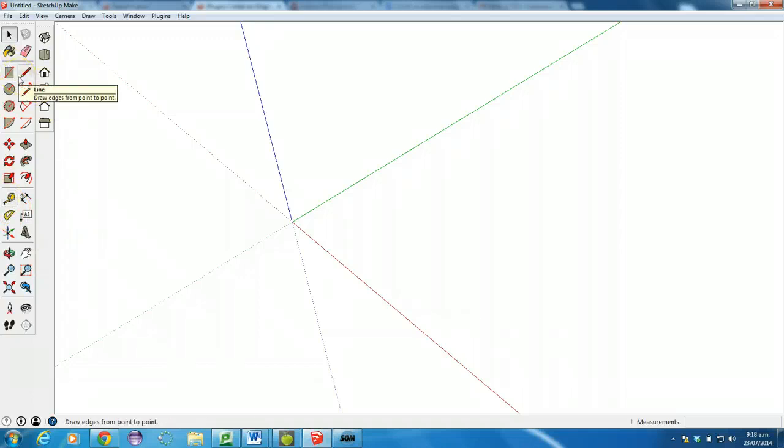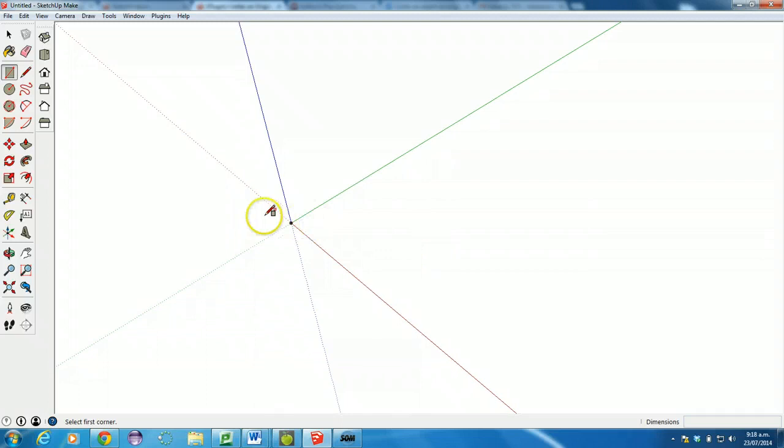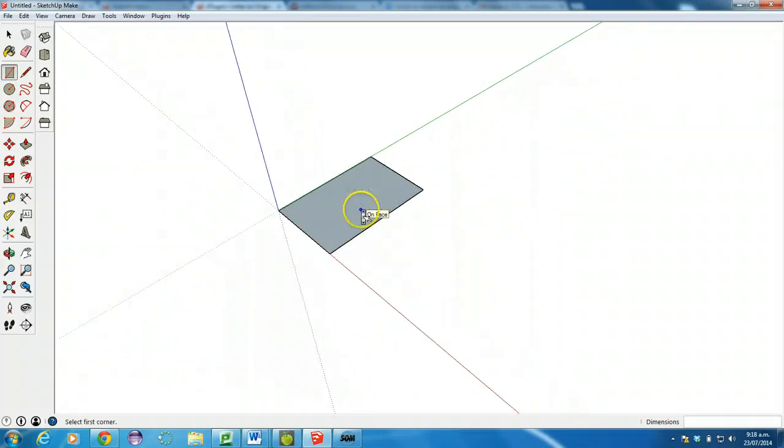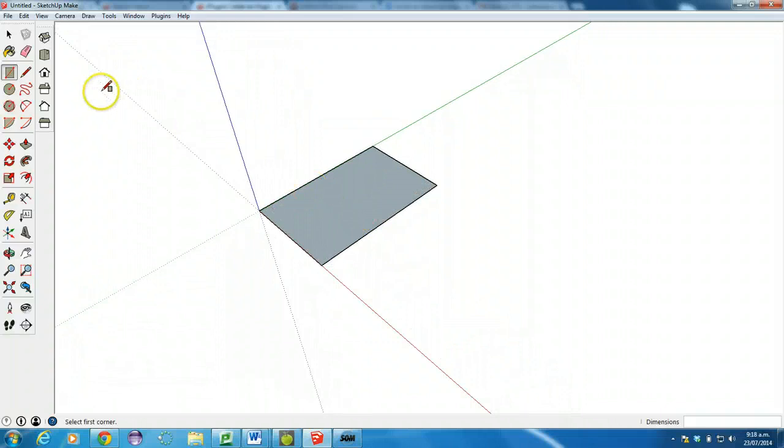So we're going to start off with this tutorial by building the easiest thing that everyone always builds when you get into SketchUp, and that's a very basic house. Now we're going to make this to scale in Unity, and so if you think of the size of a house, we're going to make a little tiny house, maybe a dog's house, so we're going to go 2 by 3. This is a fairly big dog house, and because this is in inches, it doesn't look very big. You might have to zoom in.